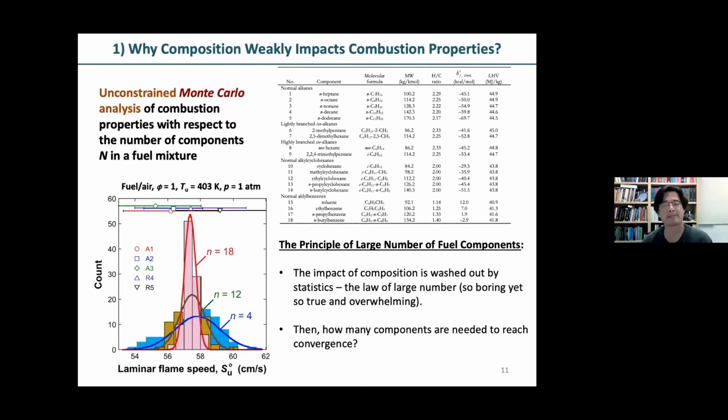Now this is not new. If you go back to look at the Norbert Peters paper back in the 1990s, this is all being told in the context of how do you even determine the Lewis number for this type of flame. So what will happen is that in this temperature region, before the flame, temperatures around 1200 to 1400 Kelvin, the fuel already undergoes pyrolysis. It's disappearing on you. Replaced by what? Replaced by ethylene, methane, propane, hydrogen, and some other minor species.